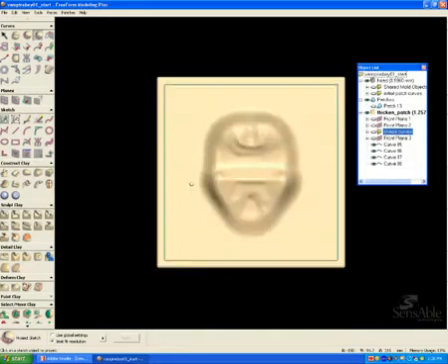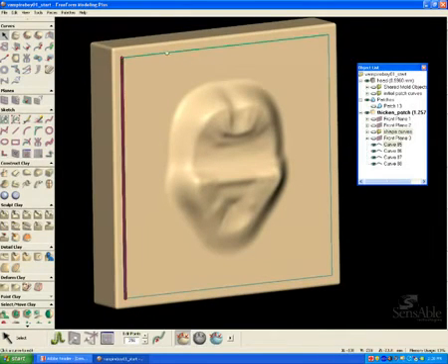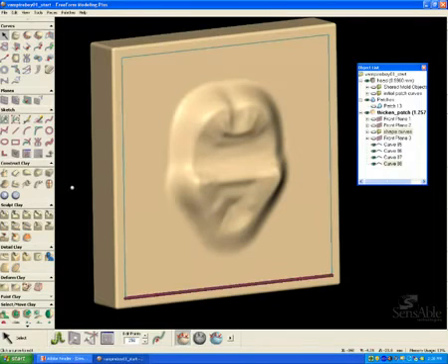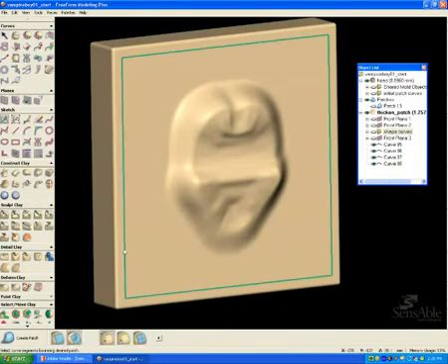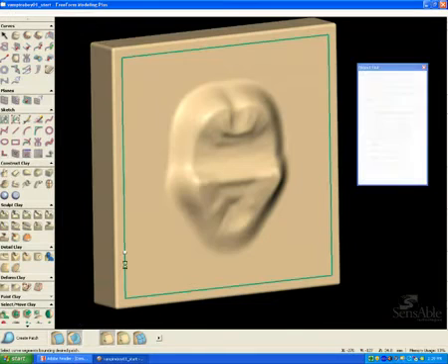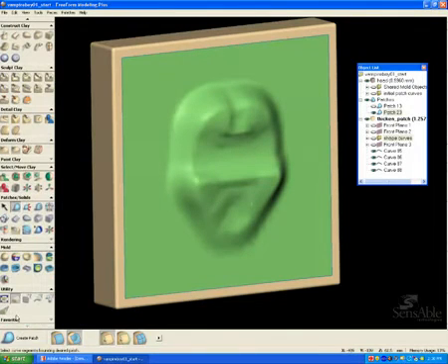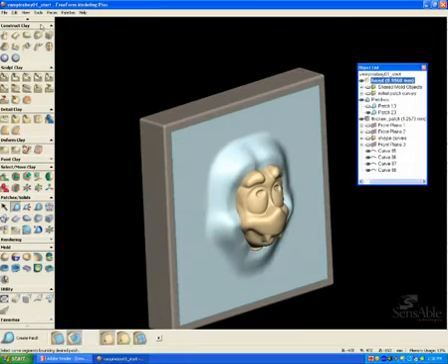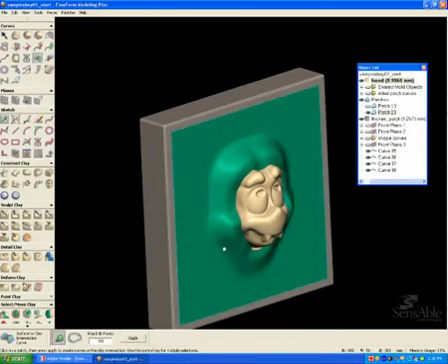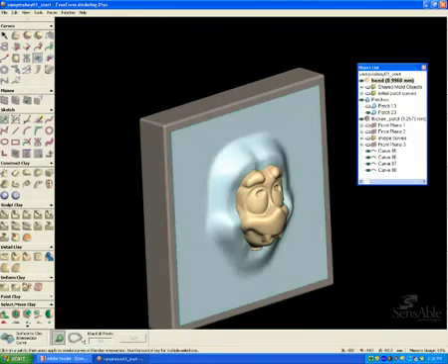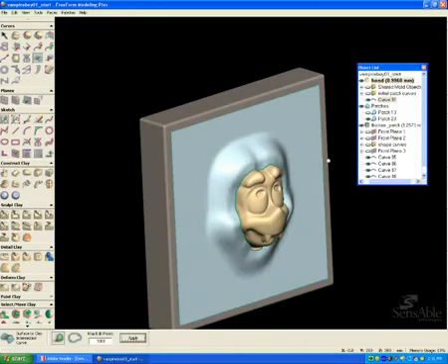And I'm bringing up a new sketch plane, drawing another square, and projecting it to the clay. And what I'm doing now is adding points to each of these lines. The reason I'm doing that is the more points there are, the more data points there are for the patch that I just created to fit to. So the patch will fit a lot better to that piece of clay. So what I did is I created essentially a parting surface now for this piece of clay.